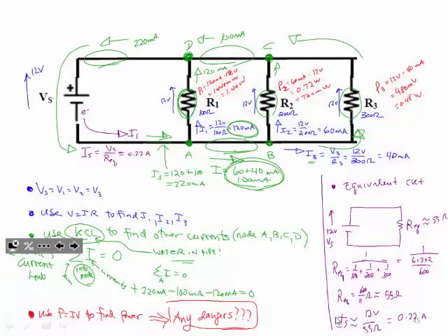Here's positive 12 volts. Here's the black wire at 0. You notice I'm color coding these things. Typically, it's red for the hot part of your circuit, the high part of your circuit, and black for the low part. So everything along this line is at 12 volts. Everything along this line should be at 0. Or if I touch across these wires, I'd see my 12 volts.